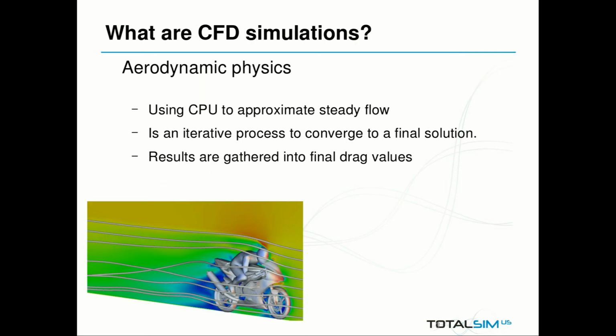For a lot of this talk, we're going to be using CFD simulations as an example. TotalSim is primarily an aerodynamic engineering firm in that we help teams design their vehicles for improved aerodynamics. That means decreasing drag and improving the downforce of racing vehicles. To help with this design process, we use CFD simulations, and we essentially perform virtual wind tunnels for vehicles to approximate the drag and the airflow around a vehicle. You can see the motorbike example below.